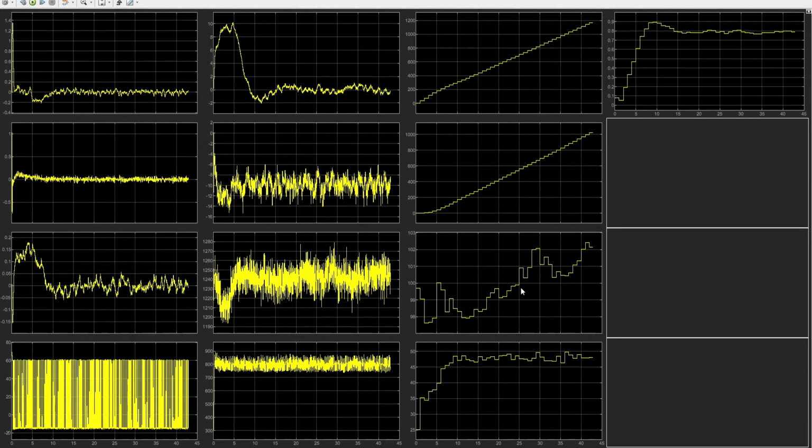And finally, the Z from the GPS, or height, also has some deviation around the 100 meter mark, which is what we inputted into our simulation. Next, we have the ground speed here, which hovers around 47, just as expected, and the heading mark, which is at 0.8 radians, which is exactly at 45 degrees, which is what we set.